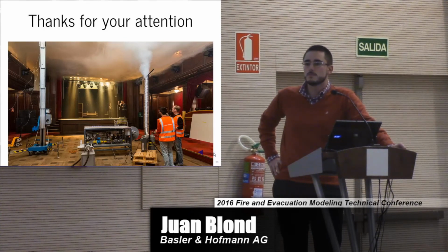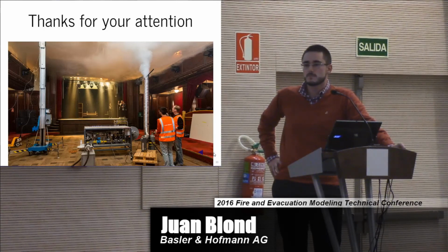Okay, all right, I'll take a look at it, because even a natural gas flame, even a small one, is typically about 10 to 15%. So 3% is very low for a radiative fraction. The other question I had is, when you measured the plume temperatures, it appeared that you had thermocouples in one quadrant. Is that right?